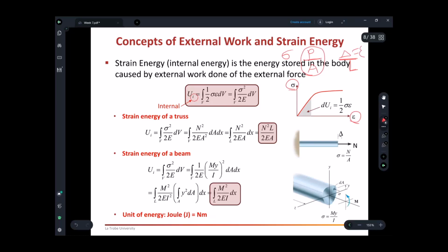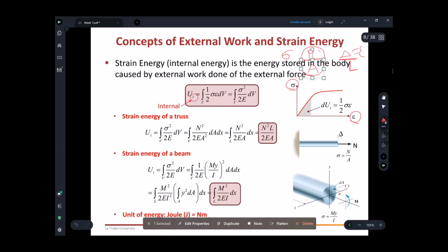Basically, when I have this pen and I apply this load on the area of the pen, that is the stress, load over area. When I pull it, there is the original length of the pen, and when I pull it there is some extra quantity, delta, divided by the original length, which is the strain. So that is the internal quantity, because we want to refer back to our original value. Therefore we have this P over delta. Still fine, same concept.